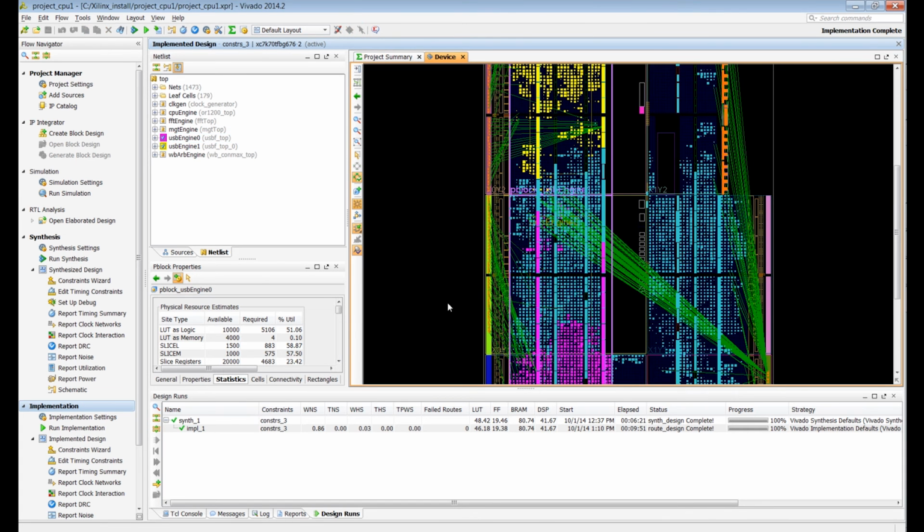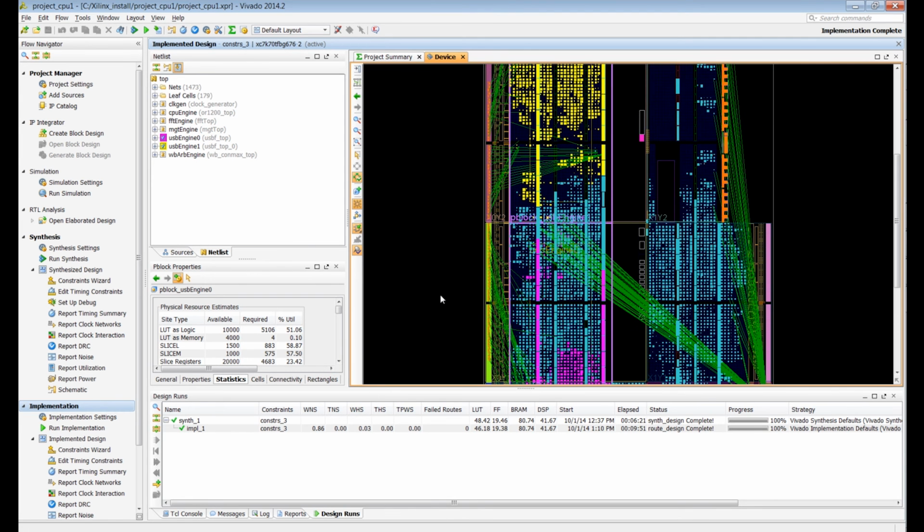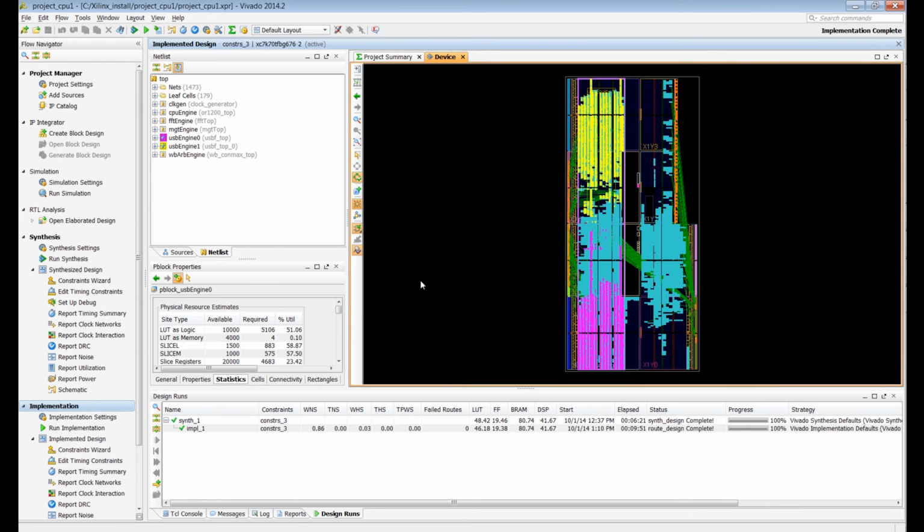There are special properties and parameters that you can put on your P-blocks to not allow other placement or routing to encroach in that space. These are primarily used for partial reconfiguration and not for floor planning for performance purposes.